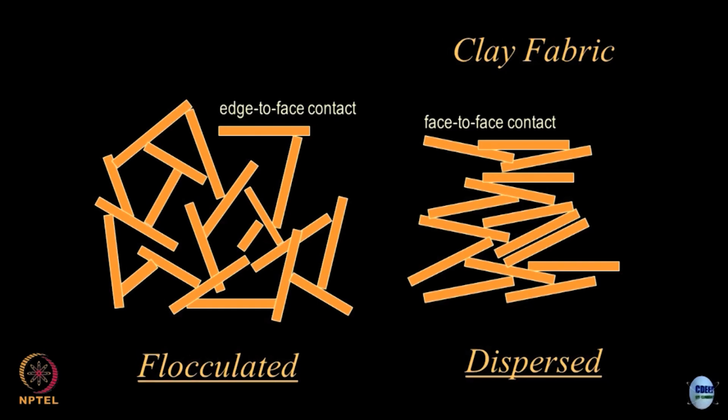What is their interest? Can you imagine? Well, these are the structures which have been created in which I can fill anything. So, these are the porous structures. Now, what I am showing here are the platelets, which is a depiction of a clay mineral or a clay sheet. Clay sheets might sit like this, that this is the sheet, the face is touching the edge of another sheet and edge is touching the face of another sheet. This is what is known as edge to face contact.